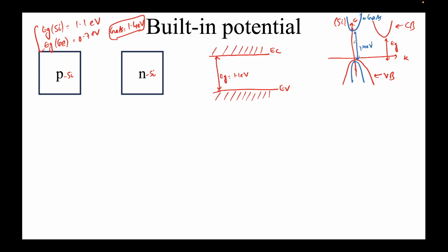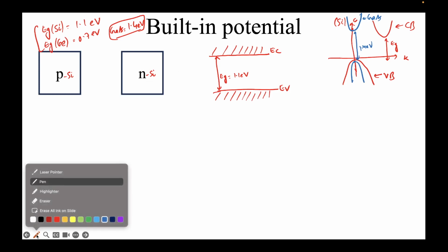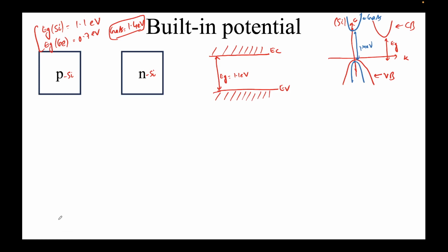For applications involving photons, specifically LEDs, for instance. LEDs are made predominantly out of gallium nitride, and for photodetectors some other materials are used. I'm forgetting fiber optics: indium phosphide, gallium arsenide, something like that. Sorry about that. Silicon has its advantages, of course, but it is not good for devices involving optics, photodetectors, LEDs and so on, because it's an indirect band gap. So good of you to ask. It was a very good point to be raised.